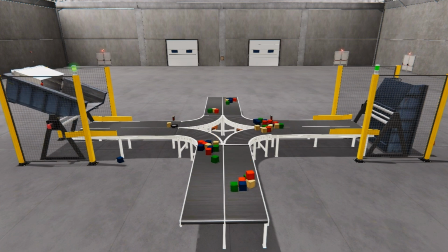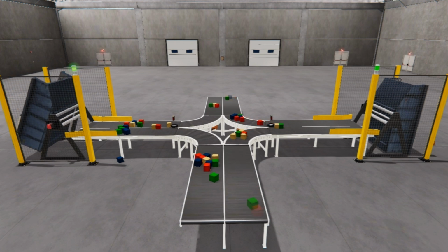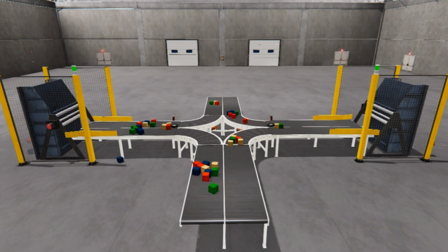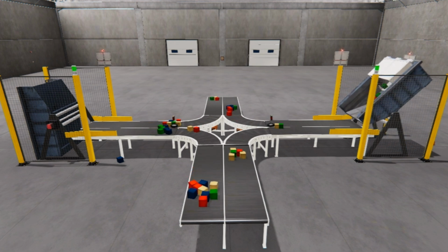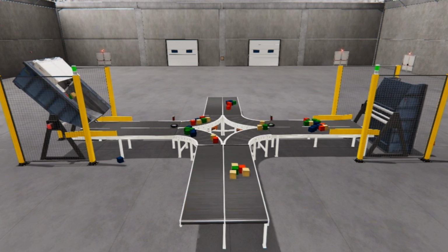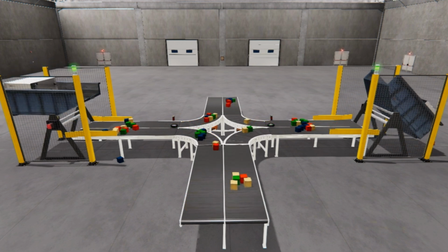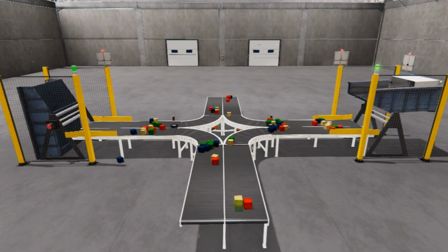When we see the internal alternate signal, the hopper is in the home position, the photocell does not see a box, and the previous box dump has reached the sensor, then we set the hopper advance and the box dump reach bit. When the hopper is in the loading position, it resets its advance signal. The box dump reach bit is a quick indication that the boxes have moved after the previous dump.